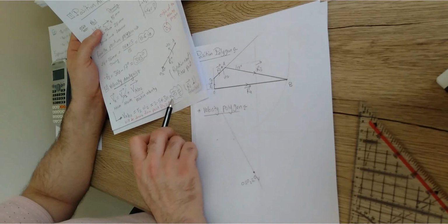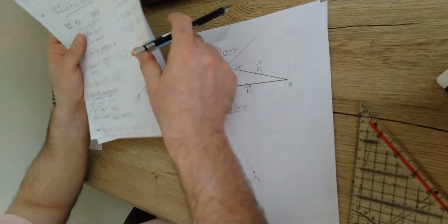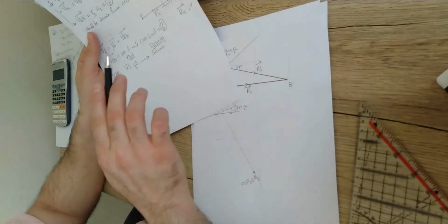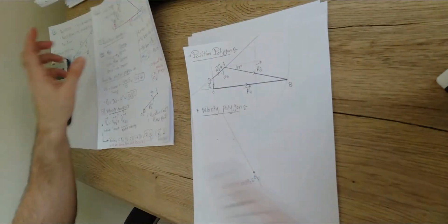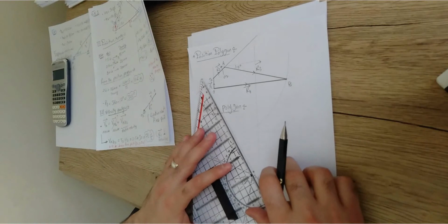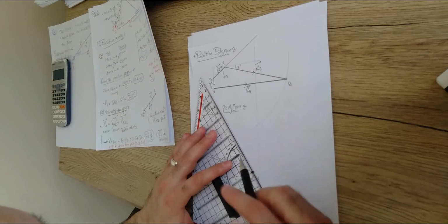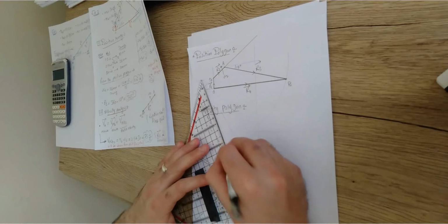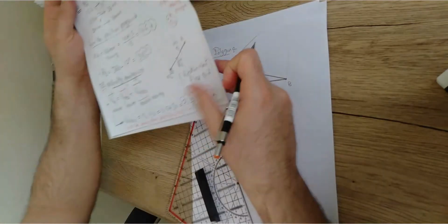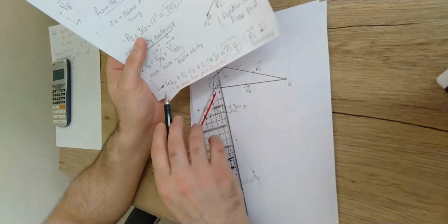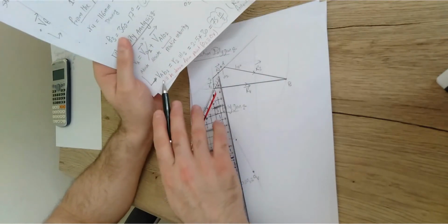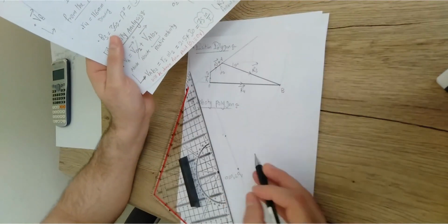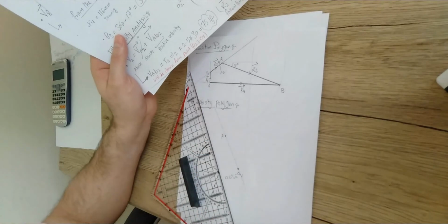And the value should be 75 inches. But after the scaling, the 75 inches per second should be represented by 50 millimeters. So what does it mean? It means that over this line, I'm going to measure a distance of 50 millimeters, which is 10, 20, 30, 40, 50, and mark a point. This point should be the other point, which is point A, because this vector should be set up between 2 points, point A and point O2. This is already point O2, so this point definitely should be point A.